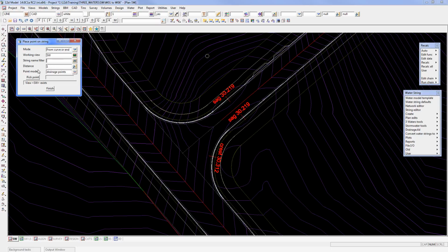I'm going to choose the KT, top of curb, primarily because the top of curb string is probably closer than any other string to where I actually want the center of my pit to go. Some people snap onto the lip of curb. I try to get my pits with the pit centers exactly where they're supposed to be built, which might not be actually on any of the strings that we've got there, but the top of curb string in this case is probably as close as any.